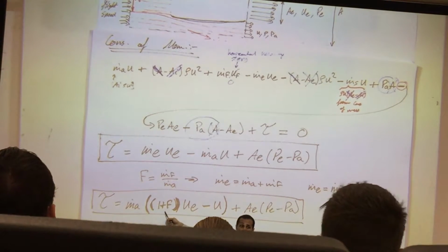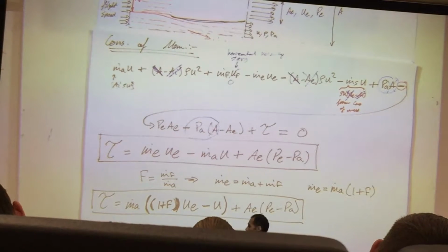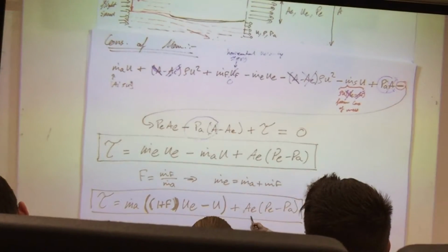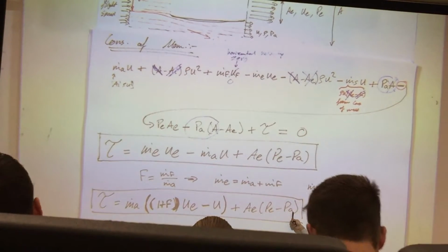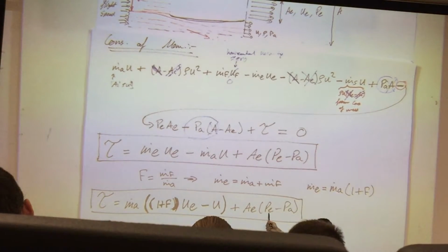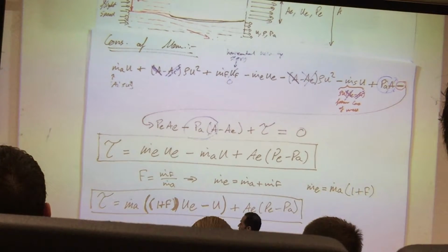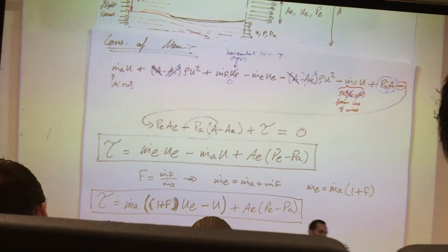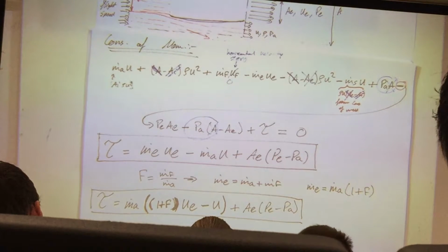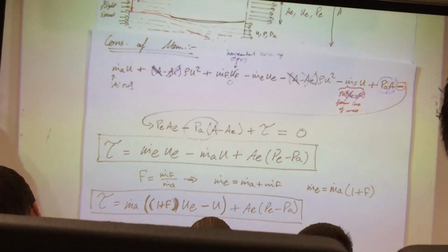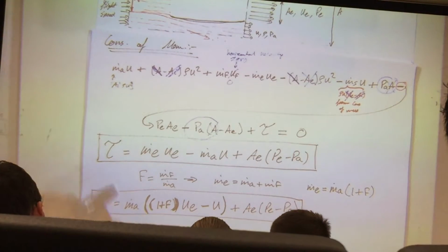This is something that you're controlling. This is a very critical parameter. And this is based on the area of your engine that you've already designed. This is the inlet pressure, so you don't control that. The exit pressure and the exit velocity are the two things that you control, through the fuel-air ratio. So from there, you have your thrust. Now this is equation 5.6 of the book.